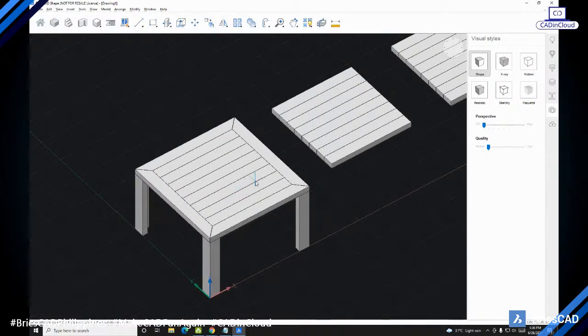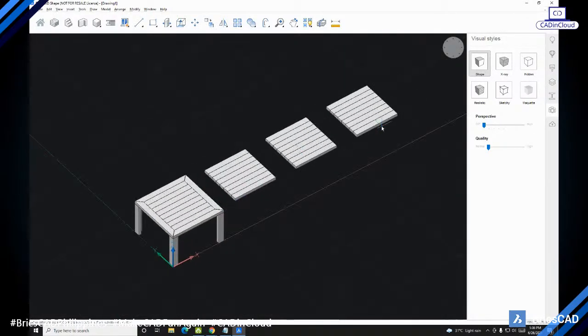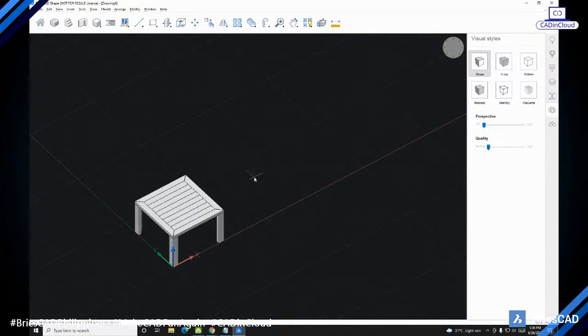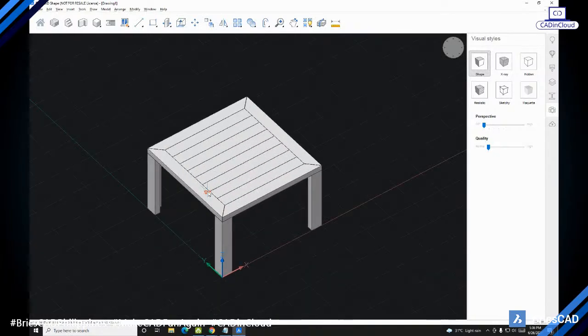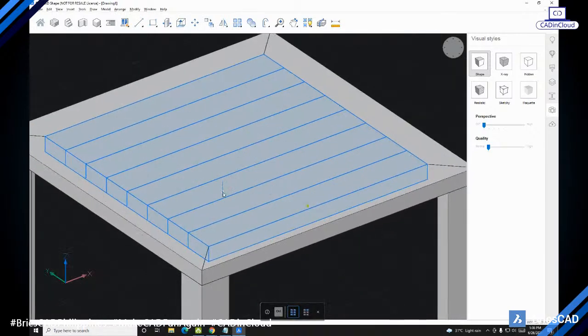There you go. Hindi naman natin kailangan yung iba. These are columns, so you are going to type COL for the columns option. Then you put 1. There you go. Then accept. Enter. Okay, there you go. So you have your table.